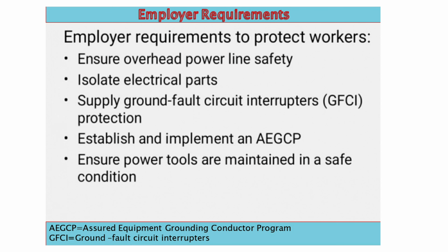Employer requirements to protect workers: ensure overhead power line safety, isolate electrical parts, supply ground fault circuit interrupter, GFCI, protection, establish and implement an AEGCP, and ensure power tools are maintained in a safe condition. AEGCP equals Assured Equipment Grounding Conductor Program. GFCI equals Ground Fault Circuit Interrupters.